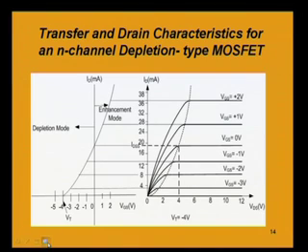So, now we understand that although the name is depletion type, basically it is having both the phenomena of depletion and enhancement. And from this drain characteristic or VI characteristic, we can project it for obtaining the transfer characteristic. If we want to plot the transfer characteristic, that is the characteristic between the drain current and the VGS, what we do is that for each of these plots, we just extend or project the saturation currents and let it meet with the corresponding VGS.